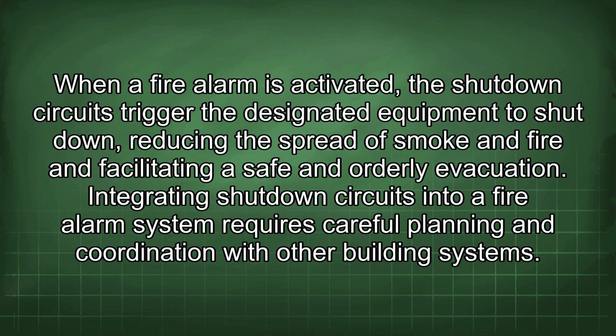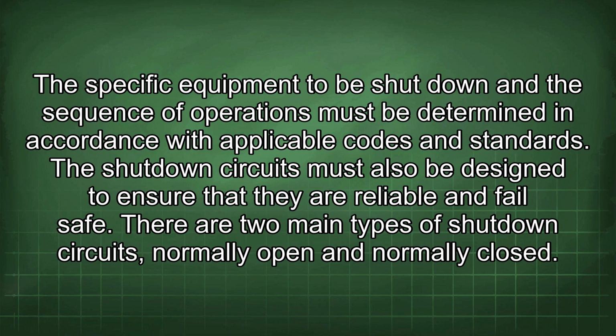Integrating shutdown circuits into a fire alarm system requires careful planning and coordination with other building systems. The specific equipment to be shut down and the sequence of operations must be determined in accordance with applicable codes and standards. The shutdown circuits must also be designed to ensure that they are reliable and fail-safe.